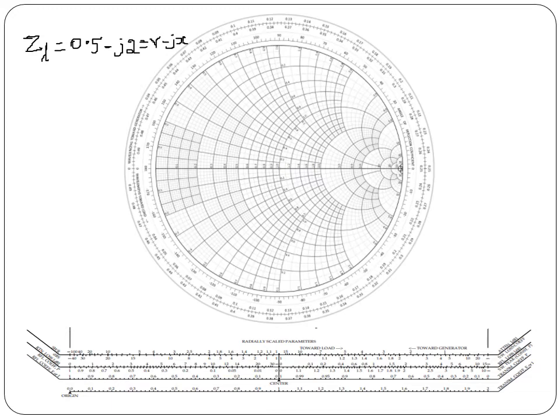Now note down R equal to 0.5 circle. Read the R circle values on the center horizontal line, where we will get the 0.5 circle. This is 0.5 circle, and it should coincide with the minus J2 line.